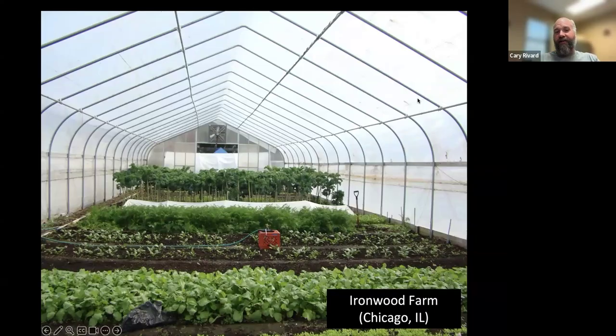Again, you think about Chicago, they get a lot of snow, right? So that snow is going to be able to slide right off of that roof, hopefully. Sometimes it doesn't, depending on how wet and sticky it is. And that's going to help protect it a bit. You can also see this tunnel does not have trusses. And so I would be a little concerned if we got a heavy snow, I'd probably send somebody out there to clean it off periodically over the course of the night or the day.